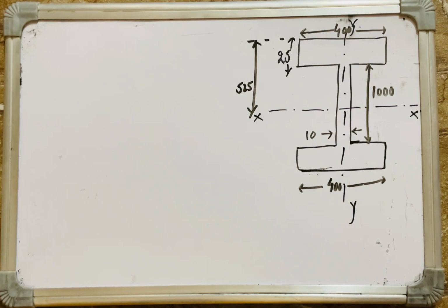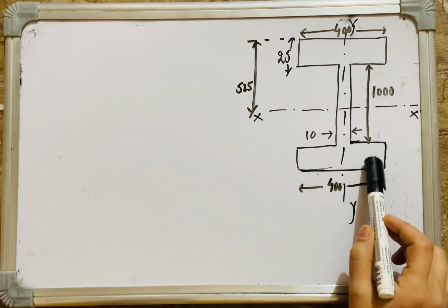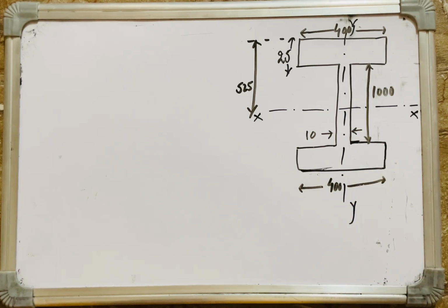Now we are designing the cross girders, and it has already been discussed that the cross girders in a steel truss bridge are designed as plate girders, with a trial section to resist the moments and the shear forces that are going to come over my cross girder. This is the trial section. We have designed it as per the moments and as per the shear force.